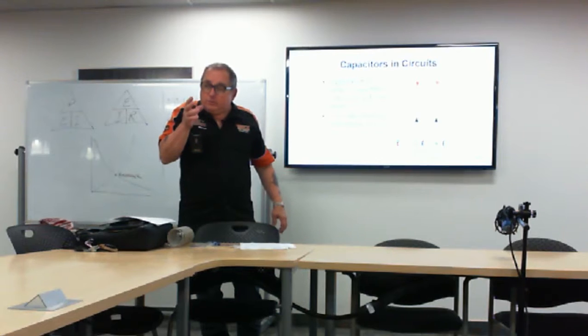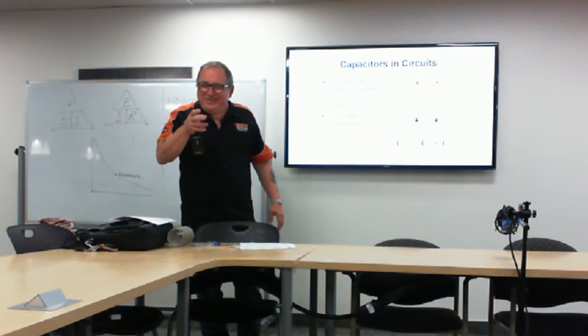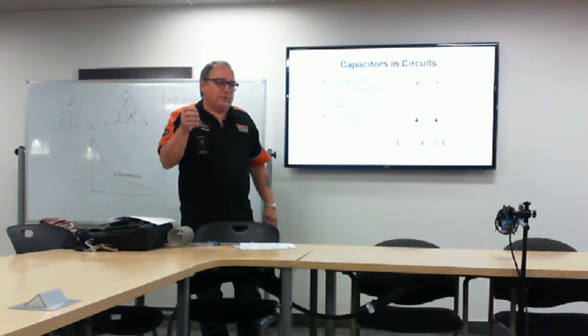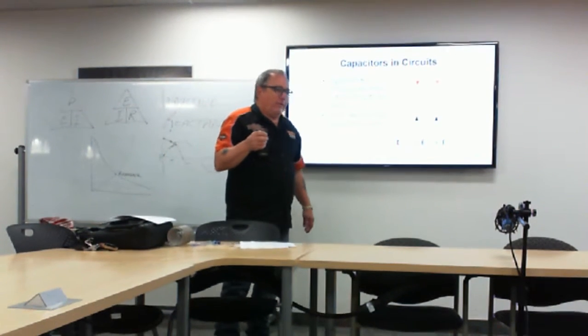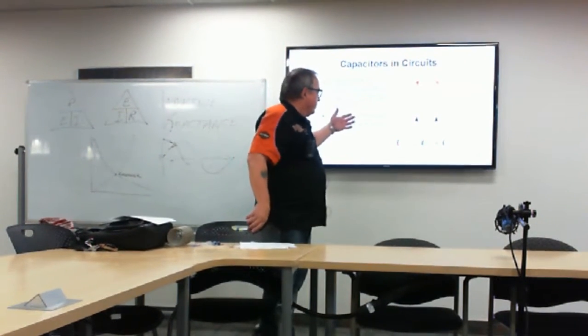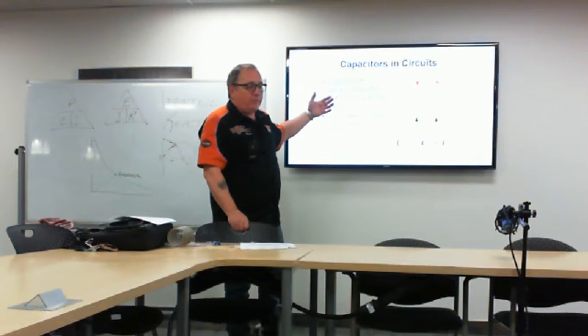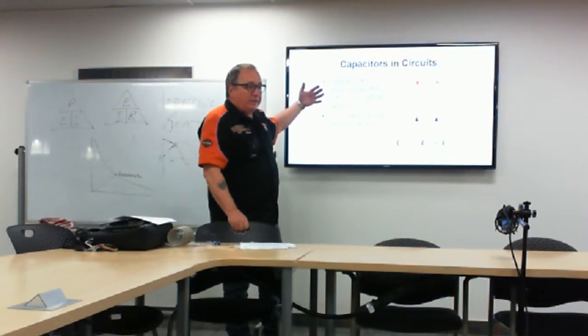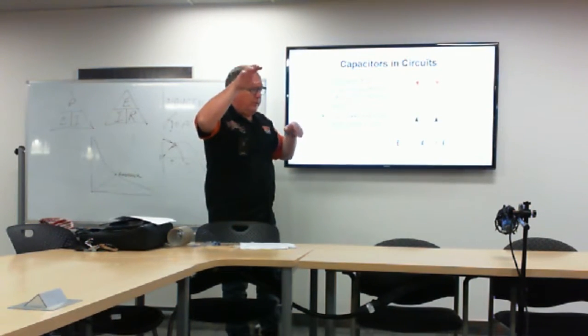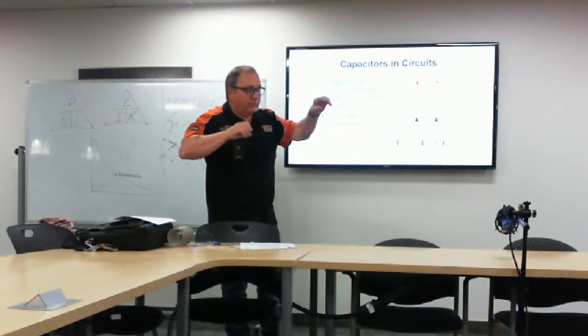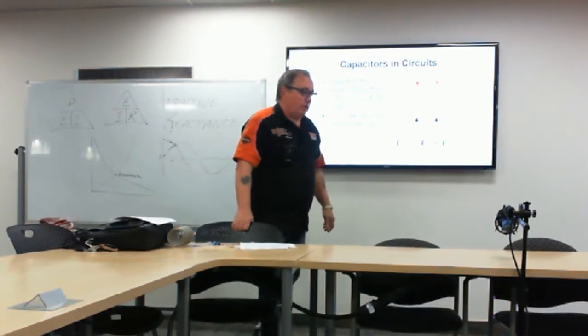All it is, what that actually is, is an inductor. Okay, and that's changing, or a transformer. I'm sorry, transformer, and that's changing from this impedance to that impedance. 300 ohm for the twin lead, 75 ohm for the coax for your television. Now we use HDMI cables and all kinds of stuff.